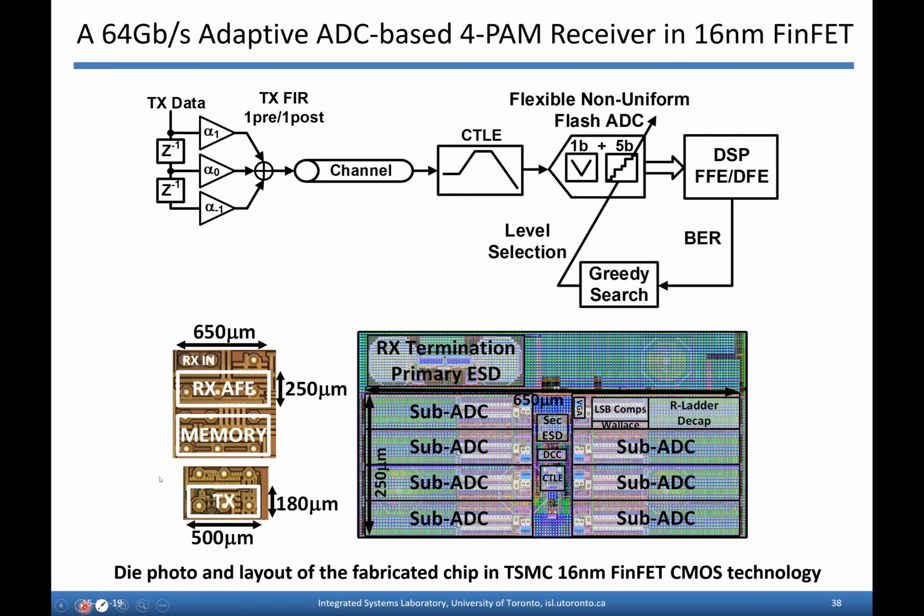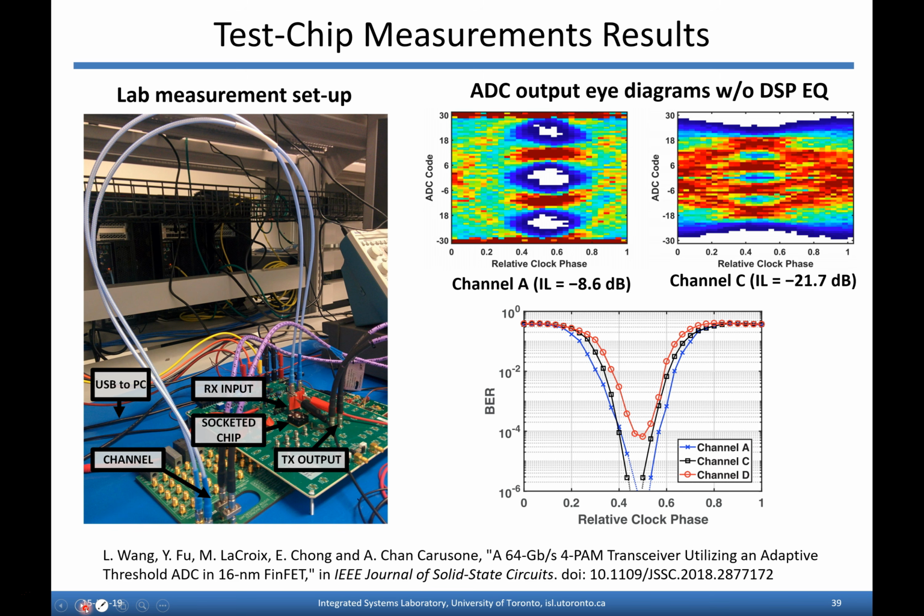So that was the case, and the circuits here involved a high-speed A to D converter, which has a lot of analog in it, which doesn't necessarily benefit from FinFET technology. Some parts of it did, some parts of it didn't, and it had to all be integrated in 16 nanometer CMOS. The layout was a huge exercise, took many months, and here's just a quick snapshot of the result.